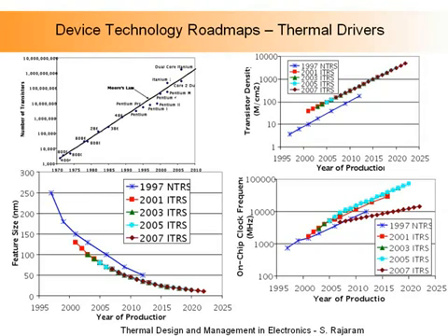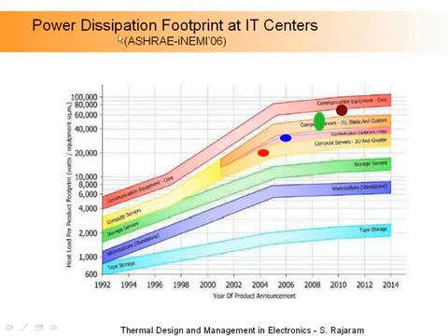Now, if you look at IT data centers, the handbook gives you the power dissipation. This is the footprint, that's the watts per meter squared over the years. And what I've plotted on that is actual products from our company. And as you can see, we actually follow, and the power levels have reached the maximum levels that are predicted here, and we're already at these levels.